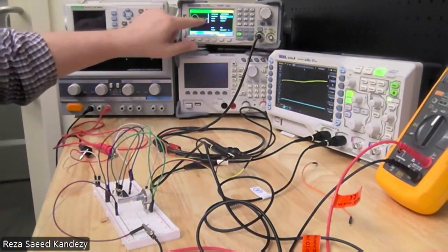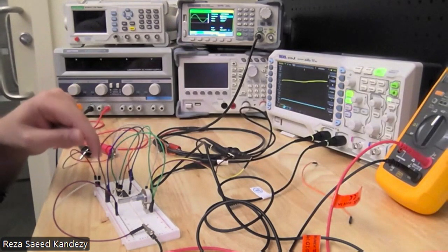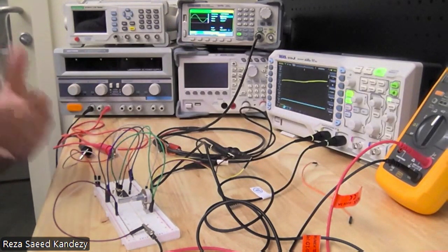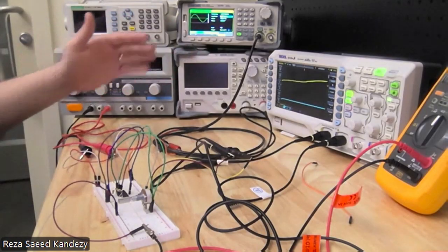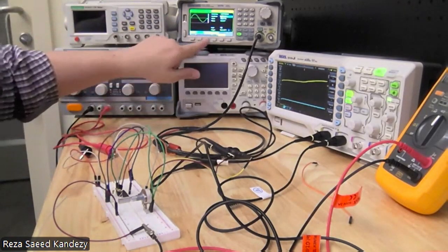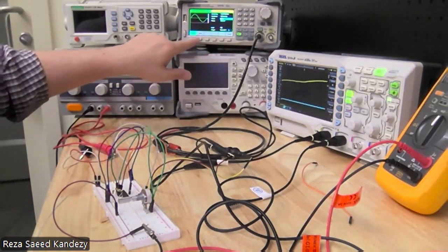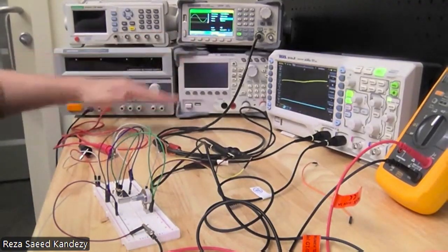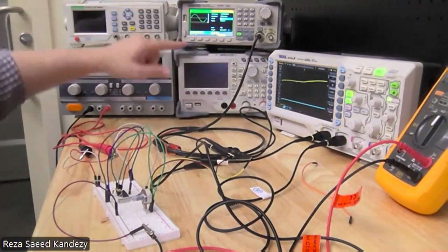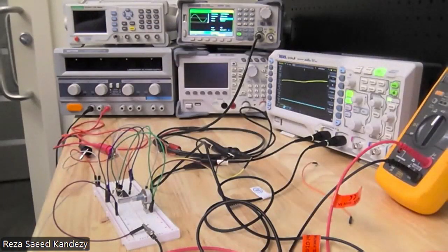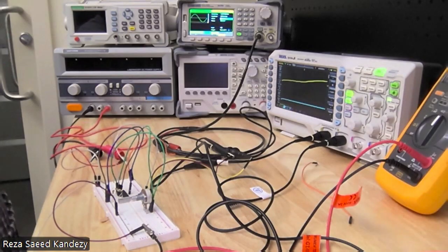In a half negative cycle, my op amp is not going to be activated, meaning it's going to cut the negative half. So what I have to do is offset the whole sine. So I'm going to offset by 100 millivolt DC, so I know every time I have a positive value in the input. Now, again, I'm expecting the voltage somewhere between 800 millivolt all the way to 8 volt.